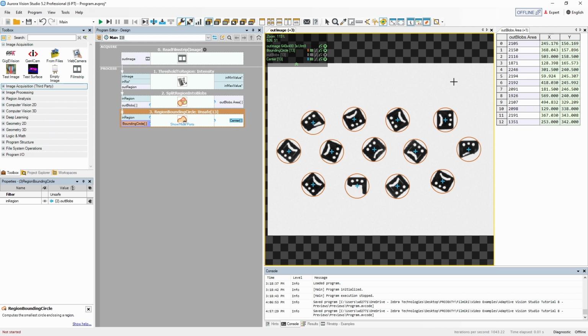Next to the array indexes icon, we have the color synchronization. When we toggle it, it will synchronize the colors in the preview window with those used by the labels. This way, it is easier to see what is what and where the specific data comes from. Notice that the circles in the preview turned blue, whereas the color of the circle centers turned orange. This corresponds to the colors of the labels assigned to these 2 data sources.